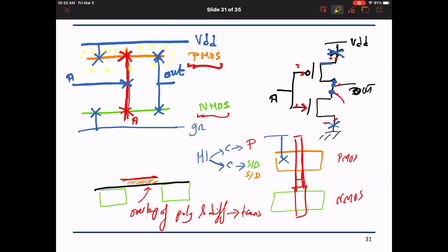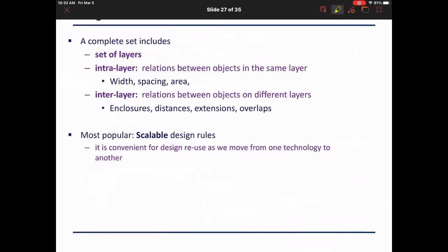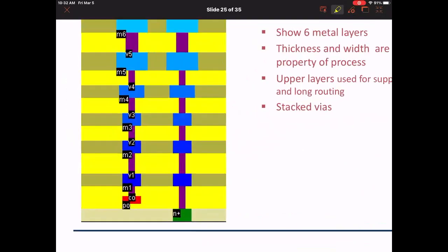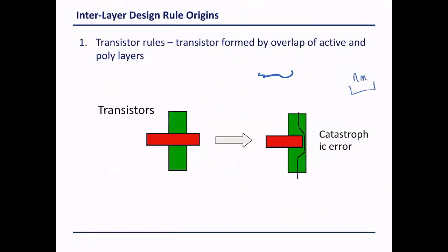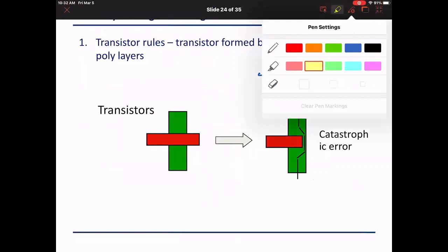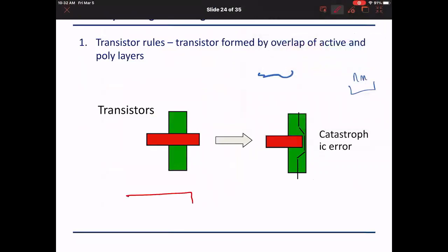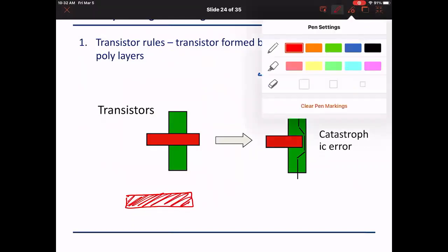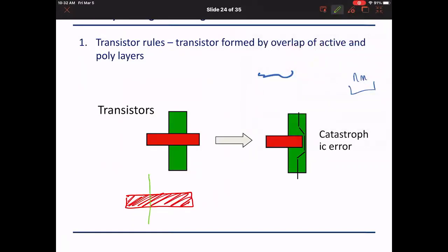Okay. Let me go back to this. This is from the way we fabricated. Under it there is no doping, and it should be highlighted, but let me show you here. Here, the way we fabricated is first I place the gate. Okay, so it gets filled. Right? And then I bring a rectangle of diffusion, but really it's going to fill here and here.